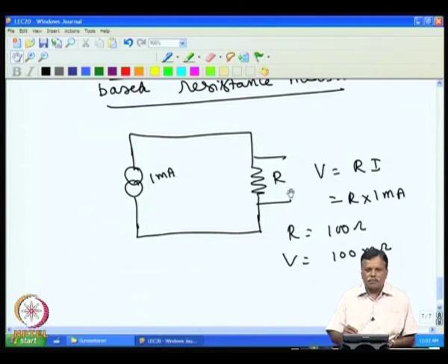That computation can be done just by scaling, or if you have a processor based unit, actual computation can also be done. And this is also linear, unlike the Wheatstone bridge technique, where the unbalanced voltage is not a linear thing. Unbalanced voltage is non-linear. So, this looks better from the measurement point of view, but there are drawbacks in this.